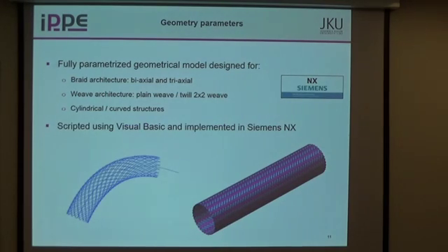In terms of yarn paths, initially it was easy and nice. We had the cylindrical model, which we were able to model a twill and a planar braid and to run our simulations. Our industry partner, which is one of our beneficiaries, said, okay, we need to be able to predict behavior also of rounded corners or rounded structures like this one, what you see on the right side.